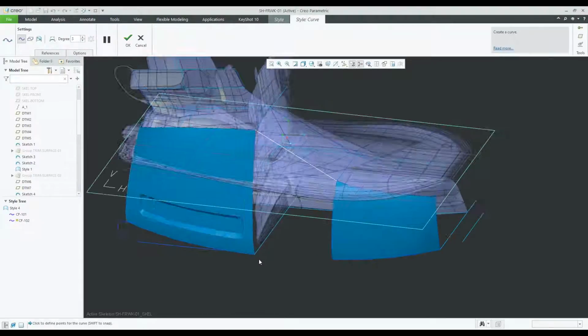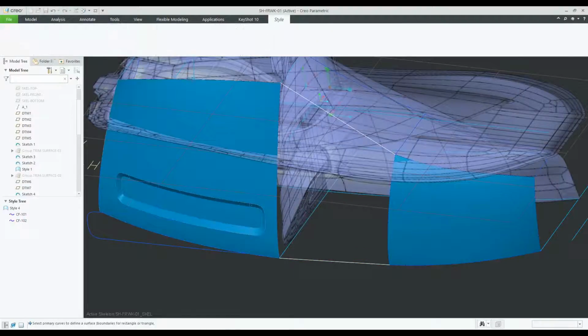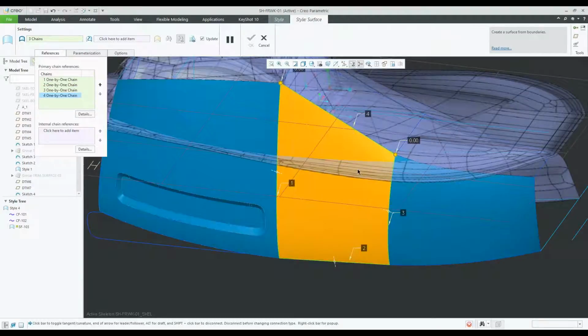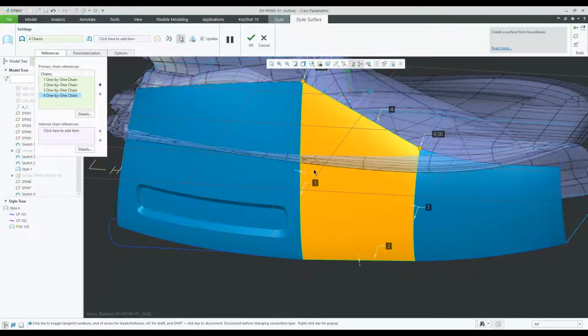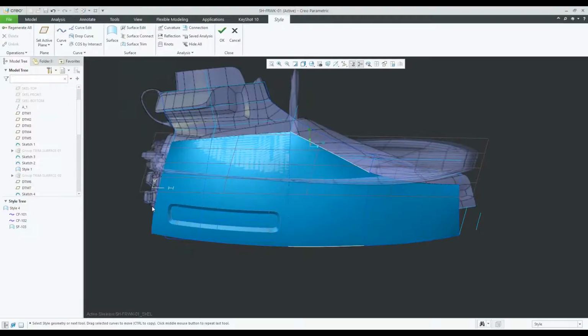just move forward here and create another edge. All right. And again, usually I can grab an edge, like in this example here, I can grab that edge, this edge, that edge, create my surface. I can adjust the tangency of that surface. I can right click here and say that should be tangent. Same thing here. So that's one way.